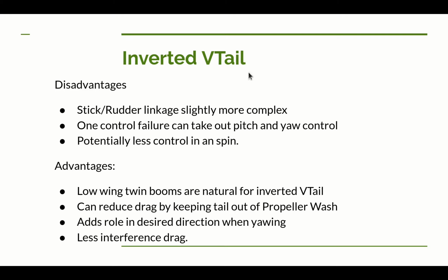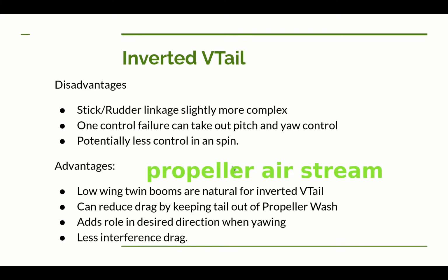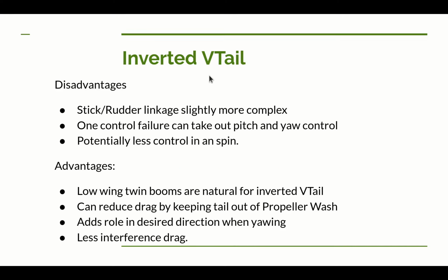Now, what are the advantages of the V-tail? Now, in my case, when I'm trying to keep that tail out of the slipstream, having an inverted V-tail matches up perfectly with having booms that go out beside each side of the prop and hook up to the bottom of the inverted V-tail. And we'll look at that here in a moment so you can see a picture of what I'm talking about. So that actually is kind of an advantage of having the inverted V-tail.